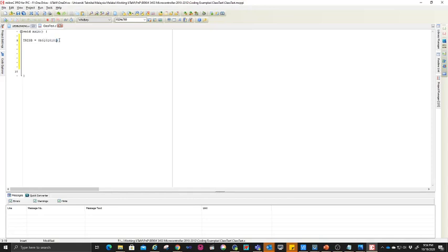So by having this statement, you are setting up the function of each pin on port B. TRISB is for digital input output. So to make life easier, first we are going to set up all of TRISB as output. Okay, so this is the first line.